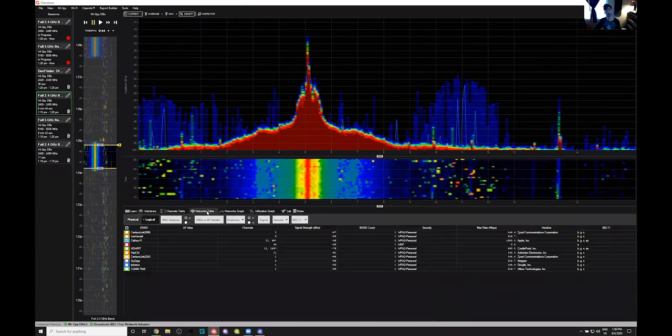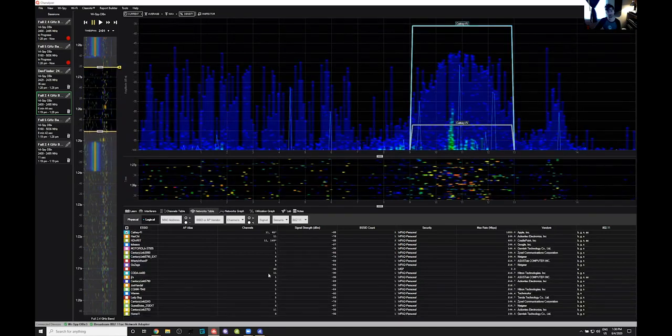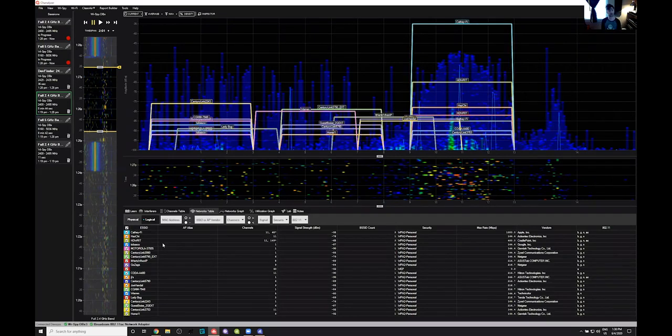One thing I want to show too is, while this interferer was talking so loudly on channel 5 and channel 6, notice the networks table down here. There's really only networks on channel 1 and 11 that are talking, and then of course those in the 5 gigahertz band, because it's completely separate. As soon as I select over here, you can see all those networks coming back to life, and I'll put check marks here. All those networks came back to life.